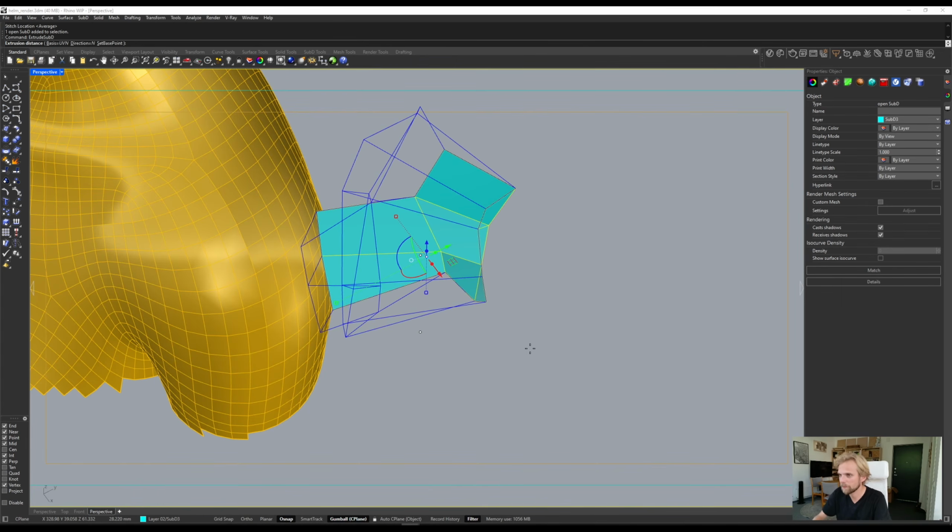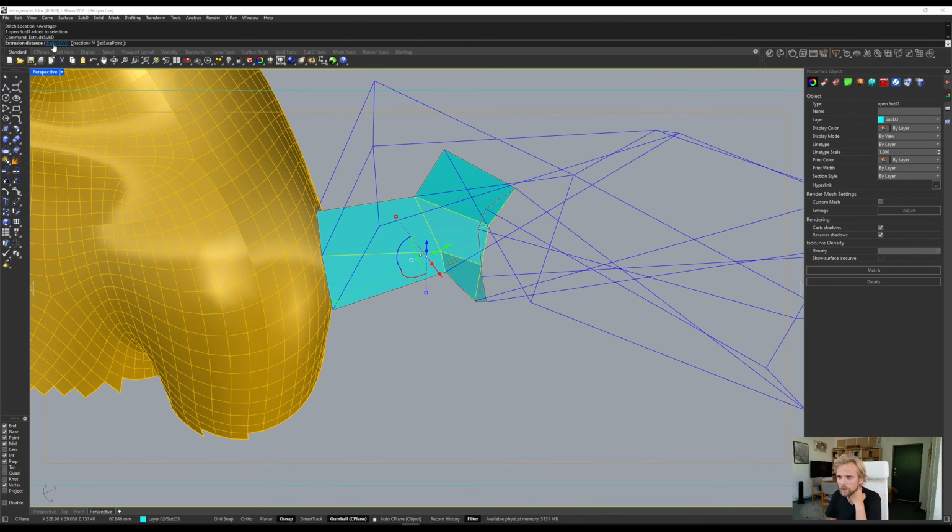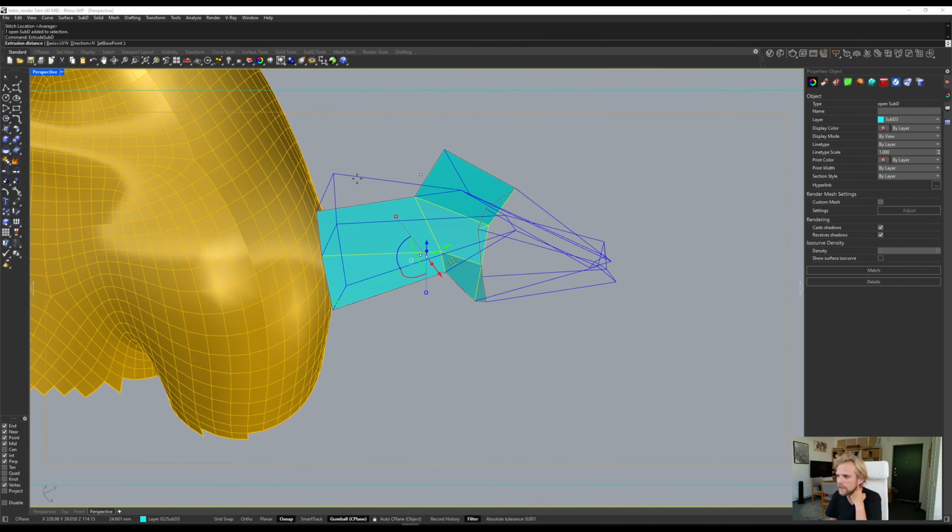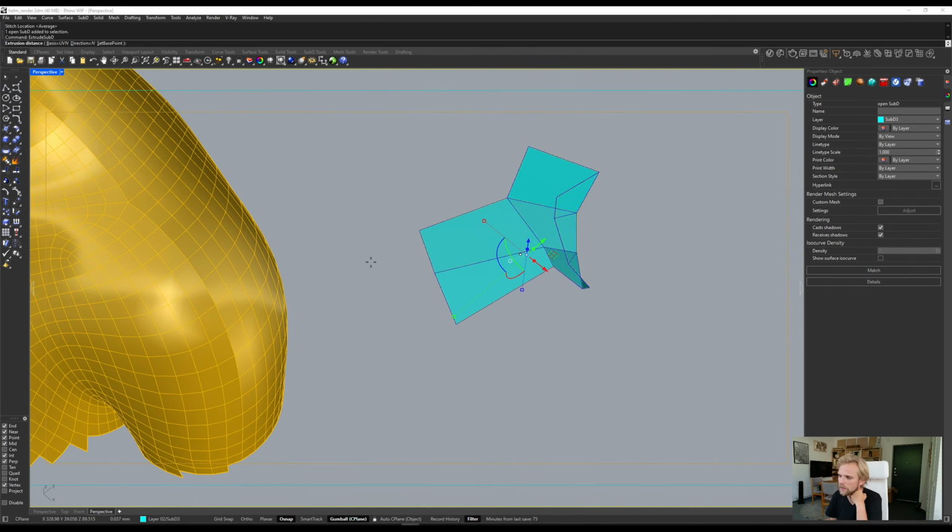The default value should be good enough for you. So basis UVN and direction normals, direction N. Meaning that every single vertex is going to be extruded according to the normals of that vertex, 90 degrees upwards, right, for that vertex.